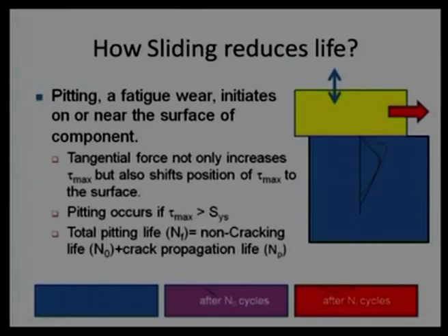When the first pit is generated, there is a compromise on the surface. So a rough surface comes, and there will be some sort of jumping phenomenon, which is going to create more disturbance in the smooth flow, and that is going to generate many more cracks because of the impacting.